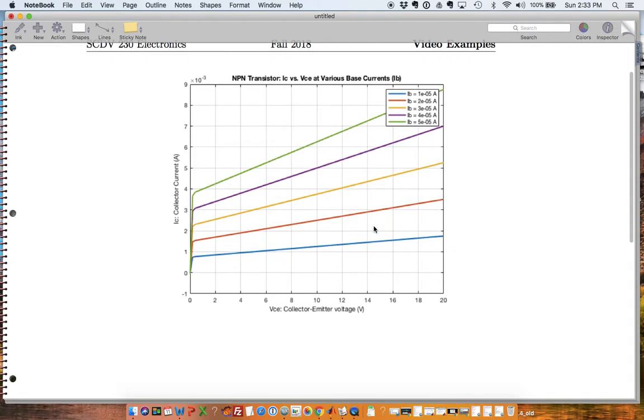And here's our characteristic curves. Each of these represents the condition where the transistor can operate for different values of IB. And these different values of IB, or my base current, will allow for different values of collector current. And so we have a max here. Let's see if I can do this as a line. This might be easier than me trying to draw it. So can I drag a line? There we go. So I've got 15 volts and 4 milliamps. So that looks about right.